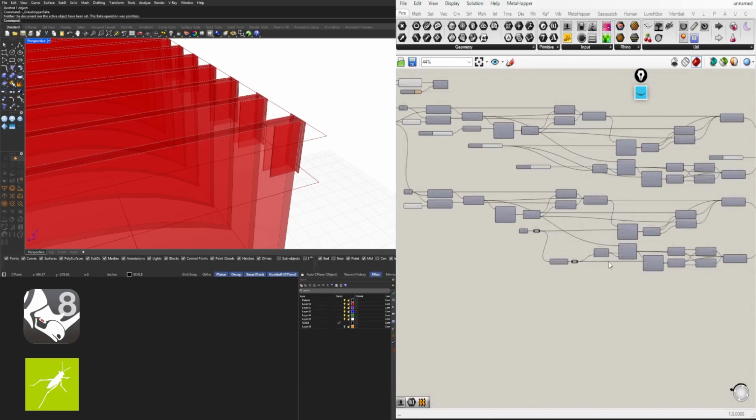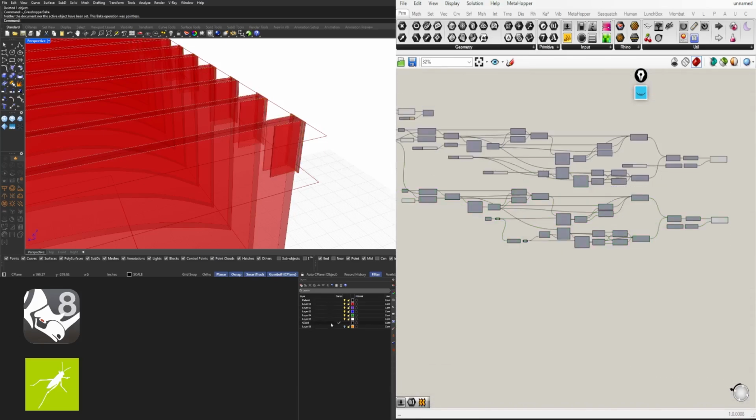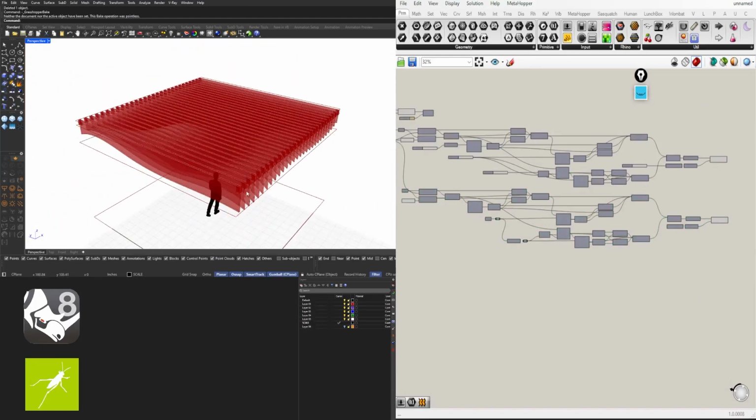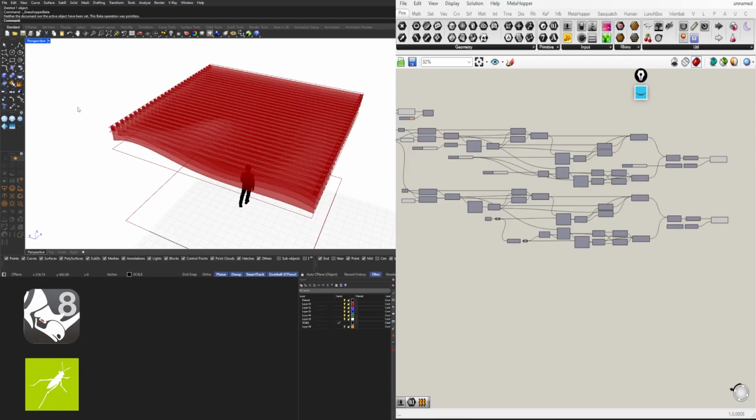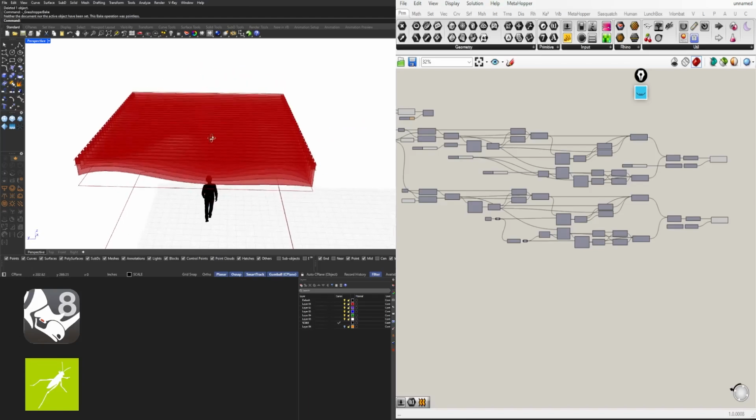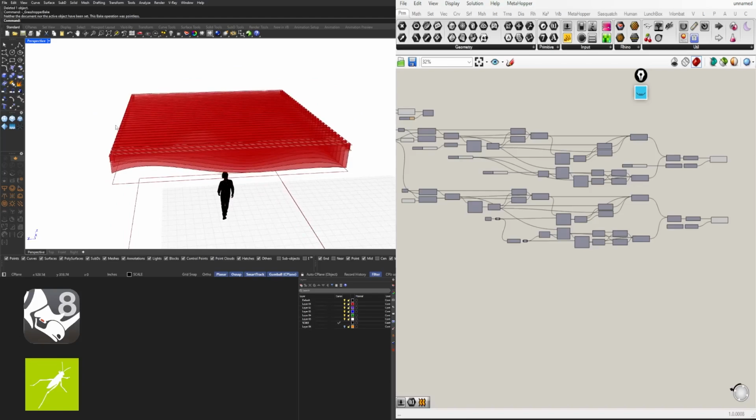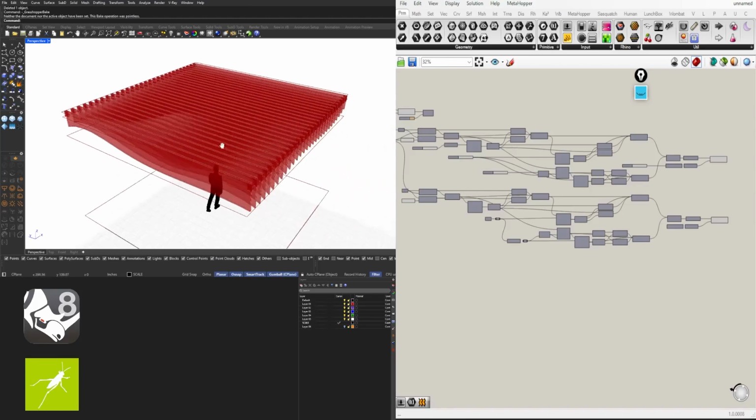Now, what's more efficient, doing this or mirroring it? Well, here's the thing. If you have a wall or a polyline that is not necessarily rectangular, then you can't mirror it. If it's not symmetrical, then you can't mirror it. So this will ensure that no matter what, it does it on the other side of where the contour is, no matter what.